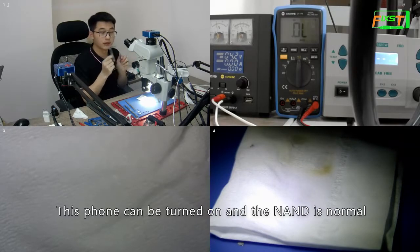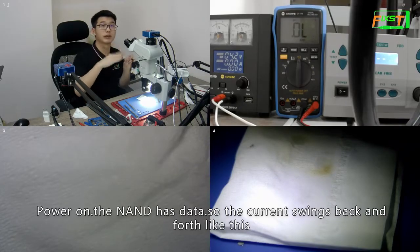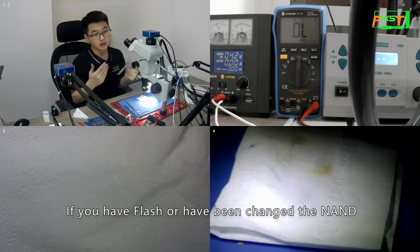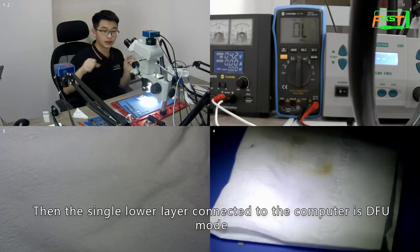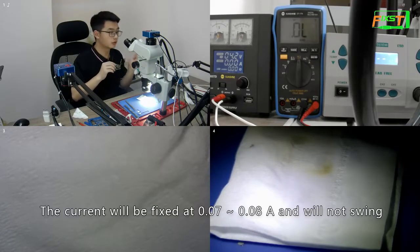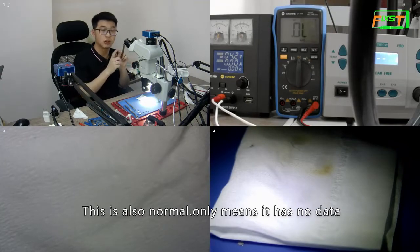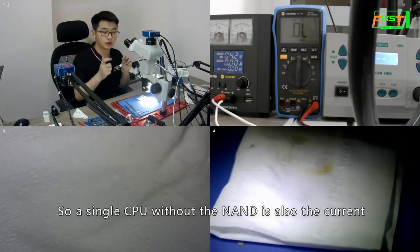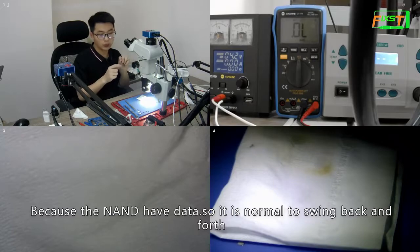This phone can be turned on and the NAND is normal. Power on. The NAND has data, so the current swings back and forth like this. If you have flashed or changed the NAND, then the single lower layer connected to the computer is in DFU mode. The current will be fixed at 0.07 to 0.088 and will not swing. This is also normal, it only means it has no data. So a single CPU without the NAND has this current, because when the NAND has data, it is normal to swing back and forth.